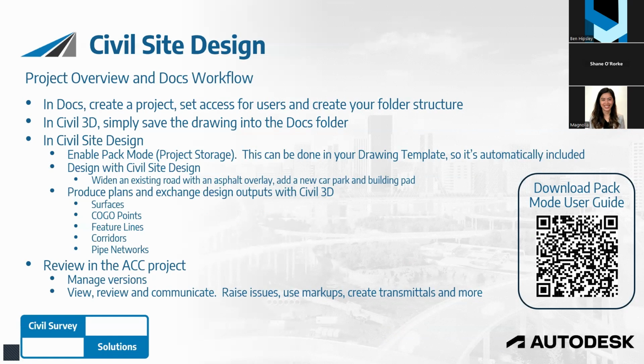We're going to look at Docs, and we're going to put the project inside Docs. It's dead simple. Before that, actually, we're a bit out of order. We're going to enable pack mode in Civil Site Design so that when we push to Docs, we're just pushing one single file. I'll also do some production outputs in Civil Site Design, just really to summarize this project.